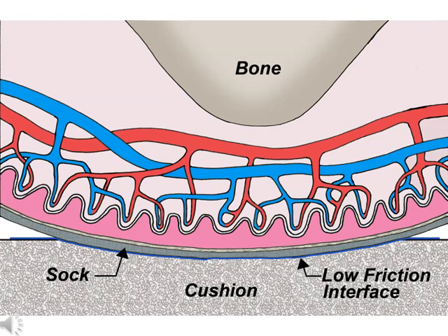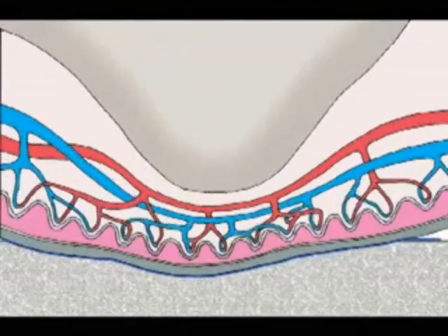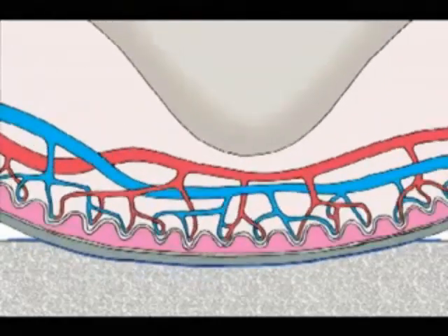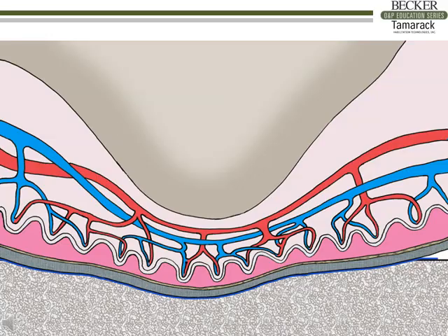A low-friction interface patch, shown by the very thin blue line, is added to the cushion insole material for the next animation. The second part depicts how the shearing distortion is arrested when the sock and skin are released at a much lower friction level to move in partial concert with the bone. Final still view showing reduced distortion in the contact support area when a lower friction load is present. The compression force is not altered.